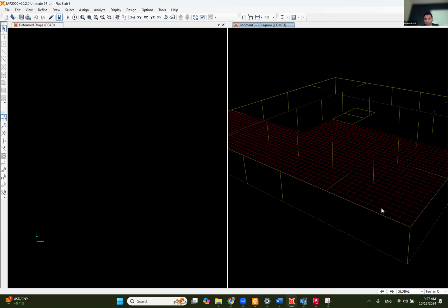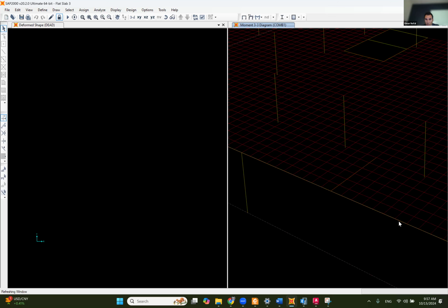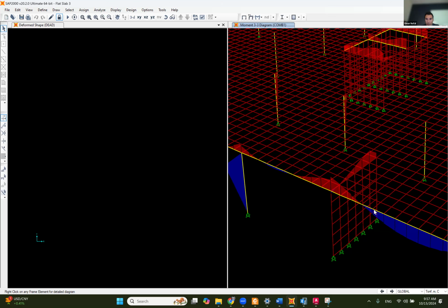If you zoom in here, you will find the bending moment on this beam. Here it's positive, and then when it comes to the wall, it's negative, and then it goes down. This moment is not continuous. If I have a full 2D model, this wall doesn't exist, and there's a hinge here, so this moment is going to be continuous. Here it's a much bigger moment, and then the moment is reduced once you pass the wall. Why? Because this wall takes some moment from it.